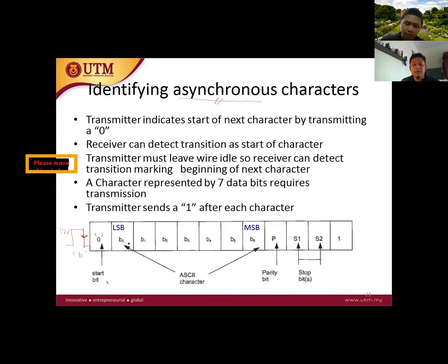After it detects the falling edge, the receiver will do the conversion, and the data is sent in a bit stream, also in reverse order of significance. This is the first bit sent on the transmission, but it represents the least significant bit, and so on.